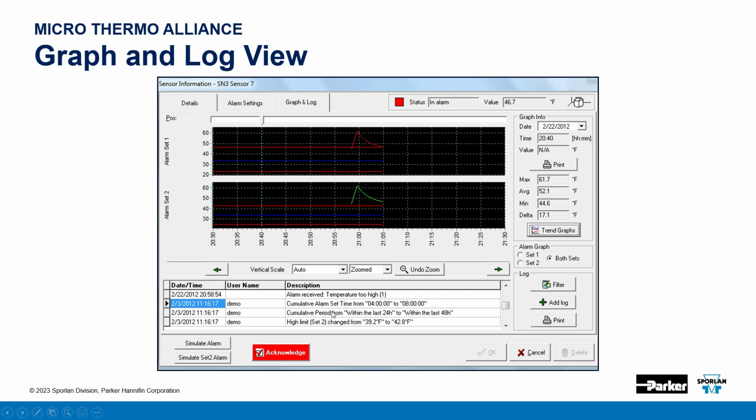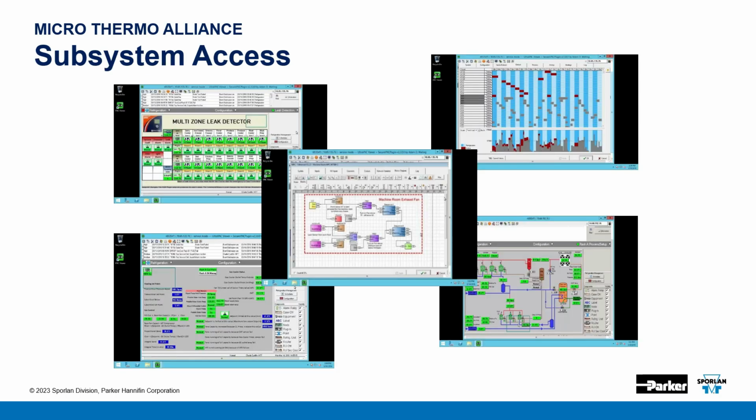You'll get the history of that device or fixture in terms of the alarms or notifications that have happened. And to acknowledge it, you simply click the button right here that says acknowledge. You'll have to enter your username again and your password and put a brief description of what you did to solve this alarm issue.